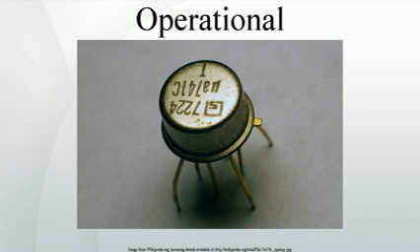Unfortunately, any design that used a chopper couldn't use the non-inverting input for any other purpose. Nevertheless, the much improved characteristics of the chopper-stabilized op-amp made it the dominant way to use op-amps. Techniques that used the non-inverting input regularly would not be very popular until the 1960s when op-amp ICs started to show up in the field.